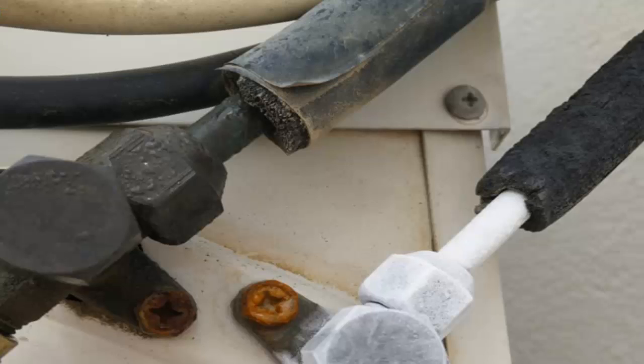4. If the thin or liquid pipe is freezing, the cause of the problem may be a lack of refrigerant or obstructions in the capillary tube.